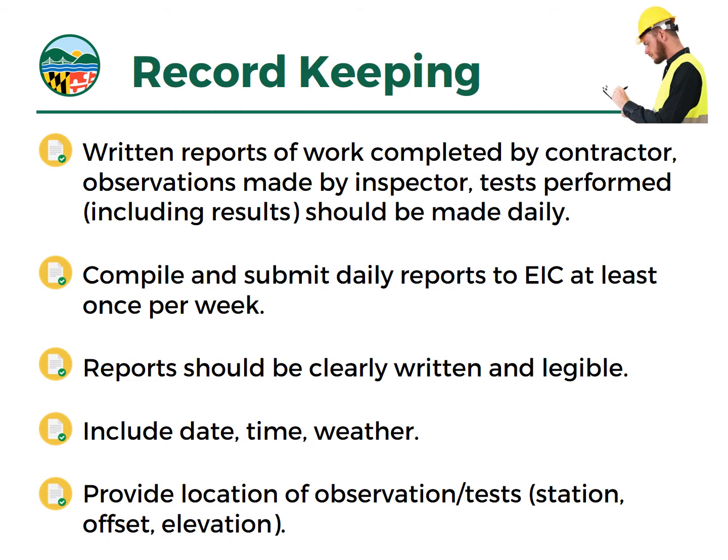I know when I was doing construction observation and testing, if I didn't get that report written by the time I left the site, if I let it sit overnight and thought I'd do it later that night or first thing in the morning, I'd forget things. I'd forget where a test was done or what elevation it was, even if I had good field notes that just needed to be transferred into a typed copy. There's always something lost. So written daily reports are really valuable for projects.